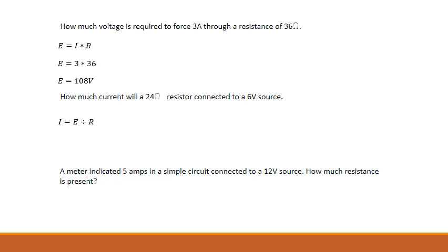So you're looking for your current, put I on the left side, bigger number E divided by R. So 6 volts, that's your source, divided by 24 ohms.